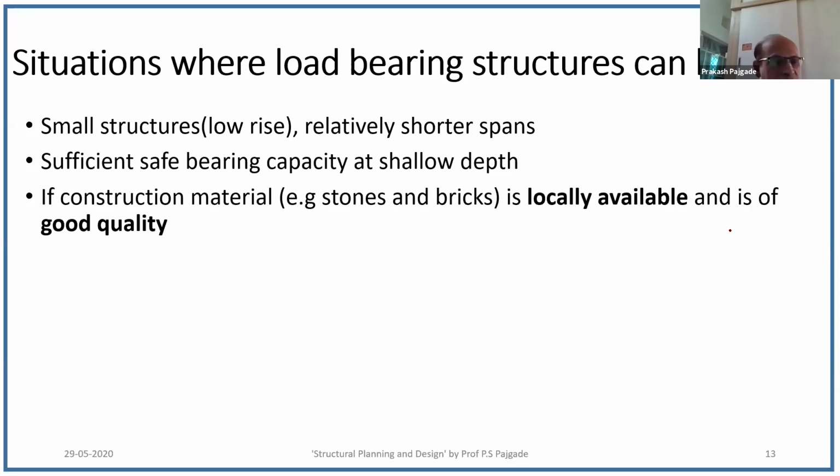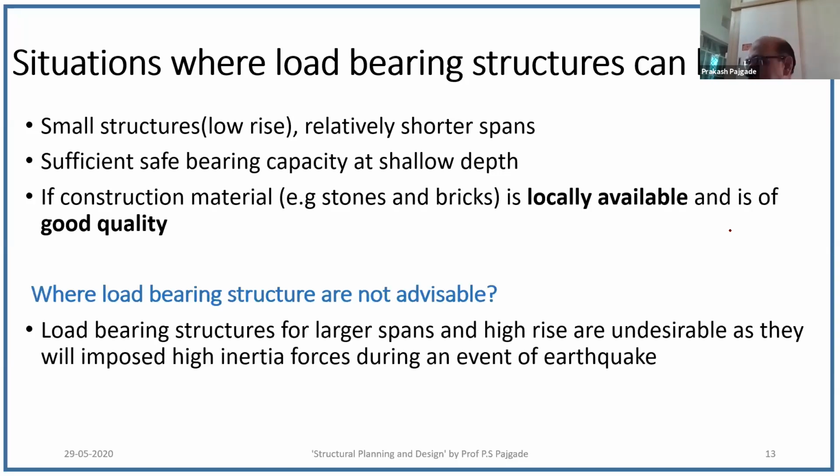When spans are quite large and we want a multi-storied building, more than 4 or 5 storied, then because of earthquake, the load-bearing building will not be a proper solution because the thicknesses required will be quite large. So it will not be better.